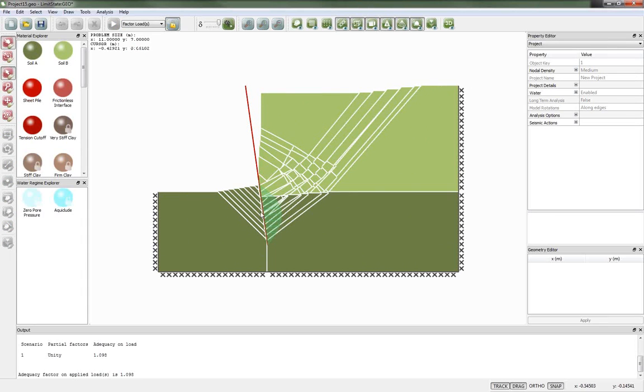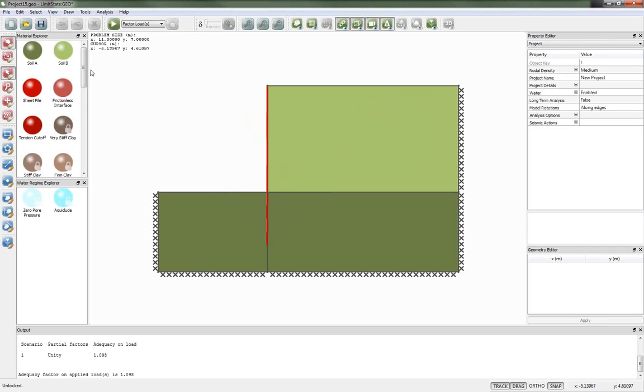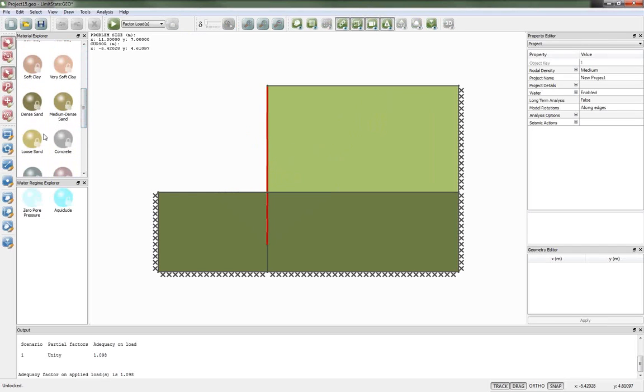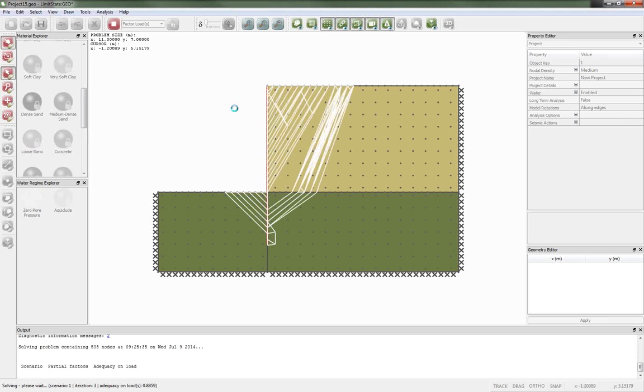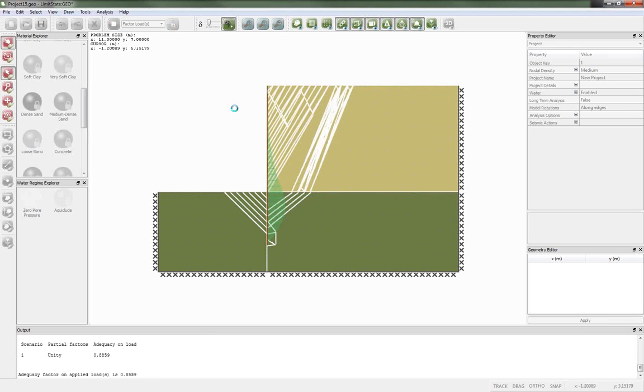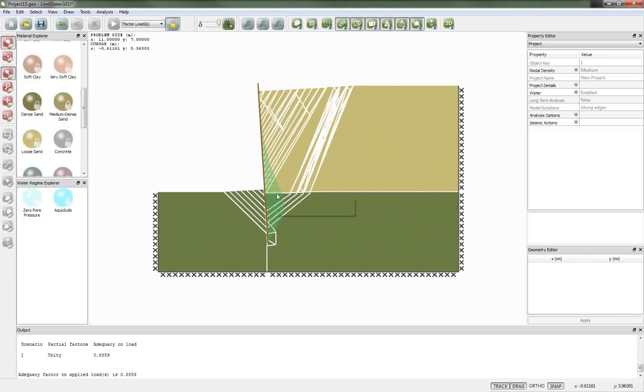This sheet pile wall is modeled using a special engineered element in the software, and it's able to identify bending moments in the wall. And also here it's identified a tension crack because this is clay. The wall can quite clearly move away from the clay, and the clay will stand up. If we put sand, for example, behind the wall, then we don't get a tension crack. The sand will just follow the wall. We get a different mechanism, and we'll get a different bending moment distribution.